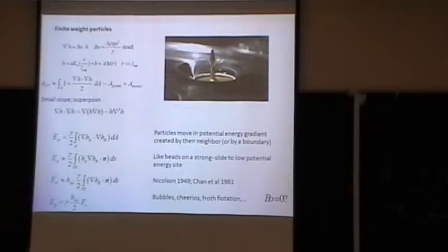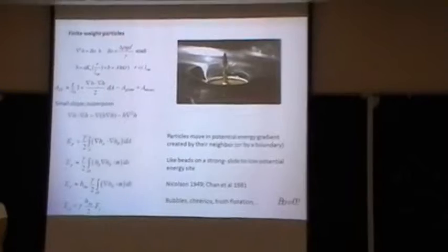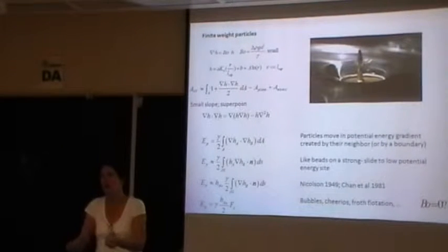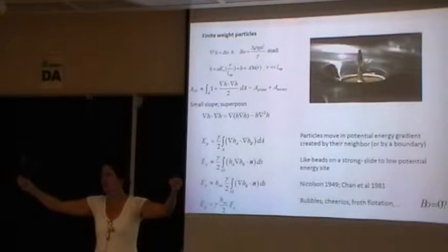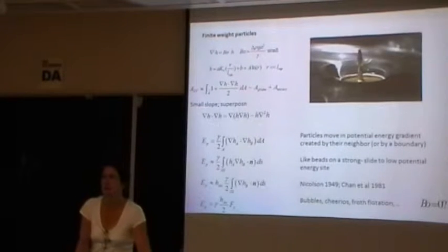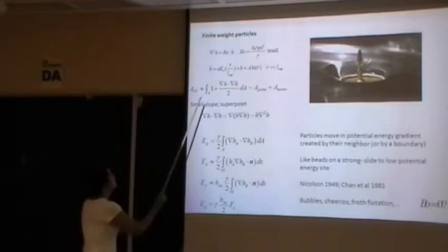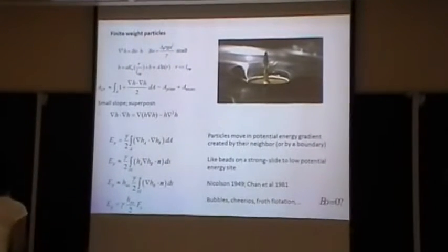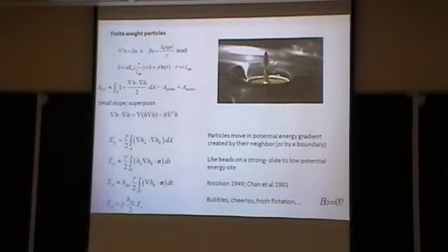Even the migration among menisci was attacked in this way. The other thing that people had seen was that if you have bubbles, say you pour coffee and you have bubbles, then they migrate up to the edges of the cup. And so Nicholson did an analysis that looked something like this. He said, the Young-Laplace equation, which is the equation that governs the shape of an interface. We talked about this last time. The mean curvature times the surface tension balances the pressure drop across an interface. If we have a pressure drop which is owing only to gravity, we can write this way.